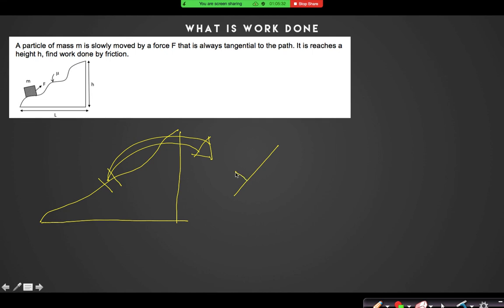You can see in this small segment what the forces acting are. Mg sin theta, Mg cos theta. If this angle is theta, I am assuming this angle is theta. Can I say that this is a very small triangular wedge? Yes, very small. Mg cos theta is the normal reaction. There is a force F. Can you tell me what is the value of friction force and the direction of friction force? Mu mg cos theta, along mg sin theta down.